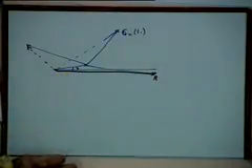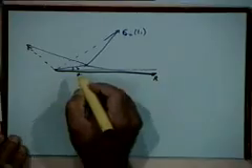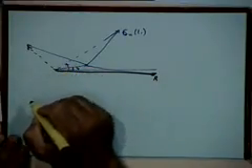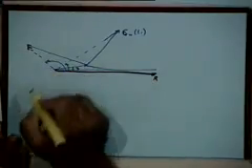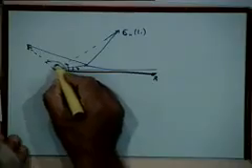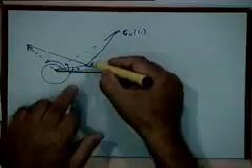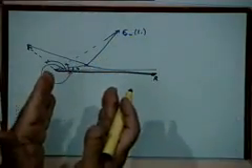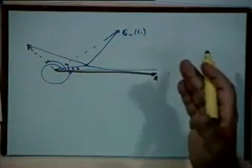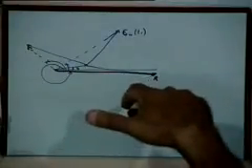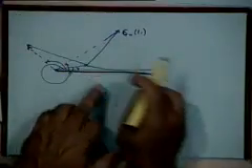So now do you see what is happening to delta psi? Look at what is happening to delta psi. This is the value of psi. The value of delta psi is this much here, right? At time t1, it is this much here, and it almost becomes 2 pi at this point. So the noise phasor within that spike duration is going from this position to this position. I have just captured 3 positions, right? One can trace the whole path. At time t1 it was here, at time t2 it was here, and at time t3 it is here.